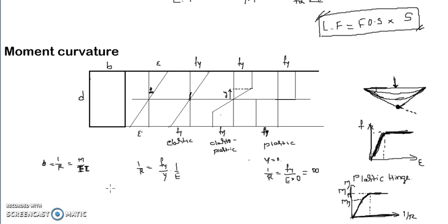It is the state of a section where all the fibers have been yielded. Now if you put any further loading or any further deformation, they simply deform. They don't offer more resistance than their plastic capacity. So plastic hinge has moment capacity up to MP.